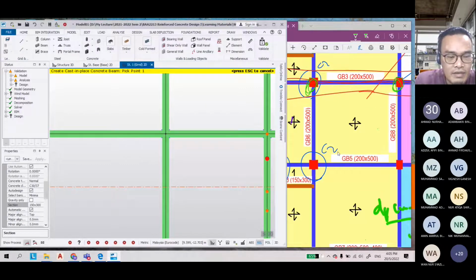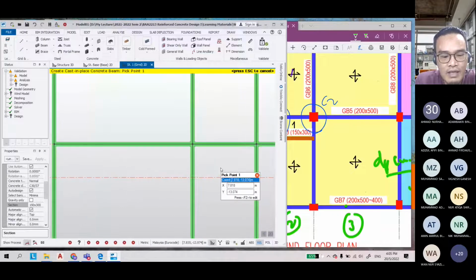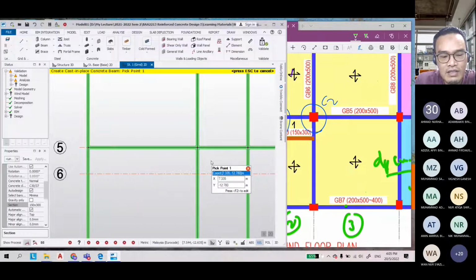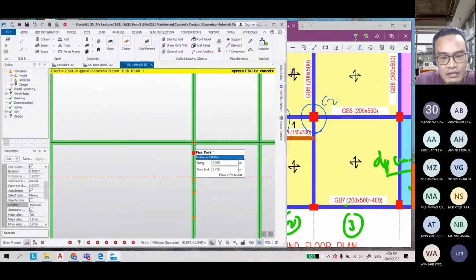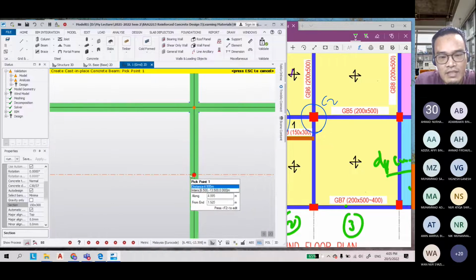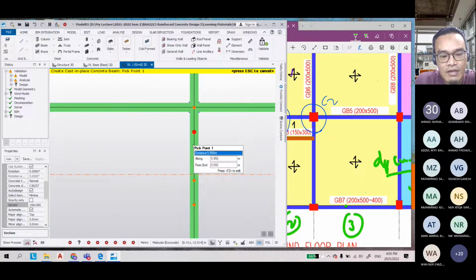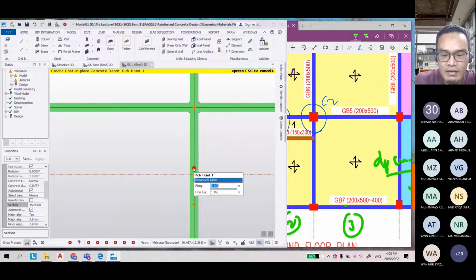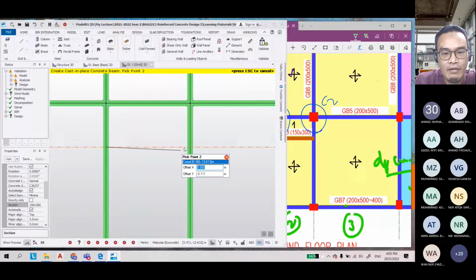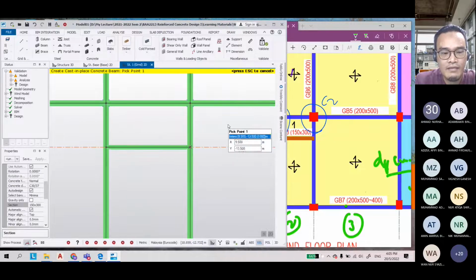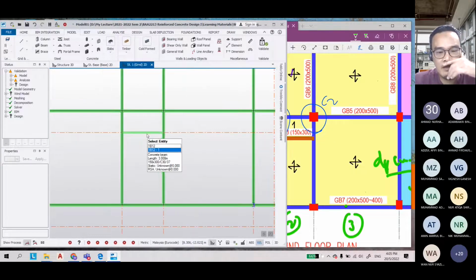So if this happens, what to do is you can click a function. Okay, here it's difficult to find the exact positions. You can click function and F2, and then you can type the right distance. Okay, so it will give you the exact positions. Now you bring it here. So this is the beam for your staircase.